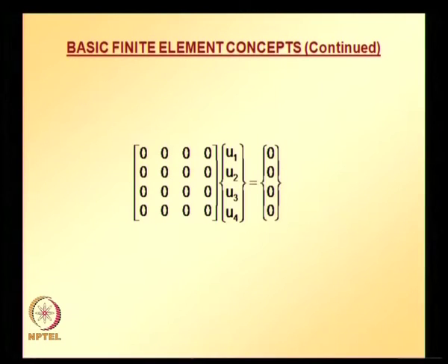What are the unknown quantities? Unknown quantities are u1, u2, u3, u4. What is the stiffness like matrix? The matrix consists, usually it is a good practice in finite element method, especially when you are coding, to initialize the matrices and vectors before you start using them, because whenever you allocate some memory in the computer for some particular arrays, earlier somebody must have used it, so some residue or leftovers will be there, and if you use it directly without initializing, it may lead to some errors. So, better you always initialize matrices and vectors.